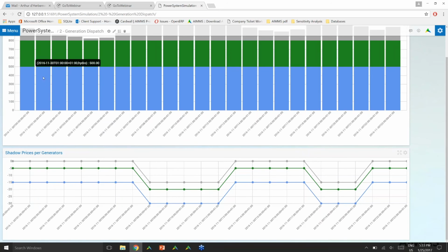The right-hand side of the hydro is 500 megawatt, okay. So this is dollars per megawatt, and $15 per megawatt, which means that if I increase the hydropower plant maximum power by 1, I would increase the objective function by $15, okay, if I do it by 2, etc.